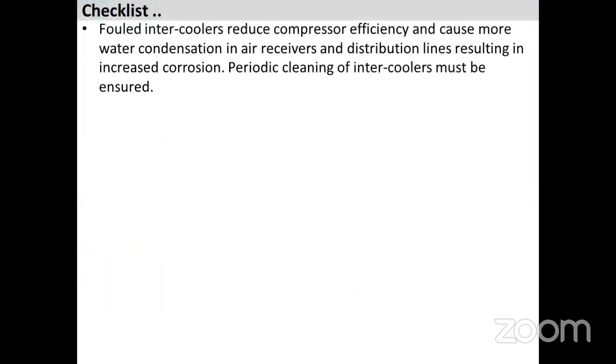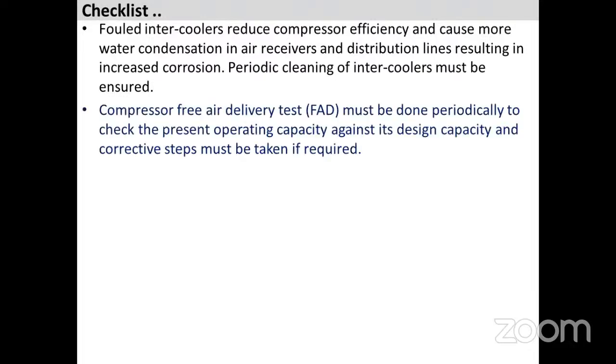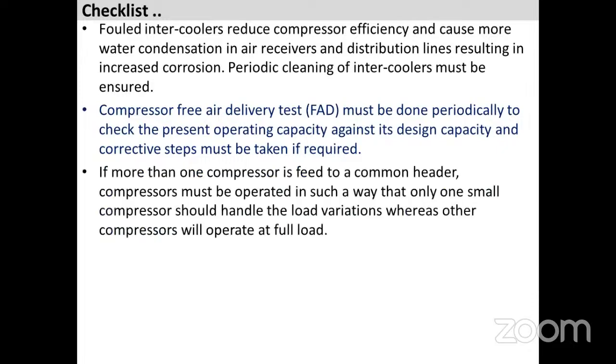We have seen this already. Fouled intercoolers. Periodic cleaning of intercoolers must be ensured. Free air delivery, FAD, must be measured periodically. If more than one compressor is feeding a common header, compressors must be operated in such a way that only one small compressor handles the load variations.